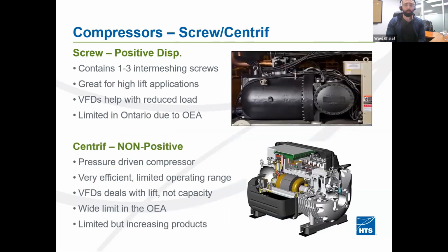So again, screw compressor is another positive displacement compressor, great for high lift applications. We generally use VFDs or slide valves to control or to modulate the load. And again, very limited in Ontario due to the Operating Engineers Act.